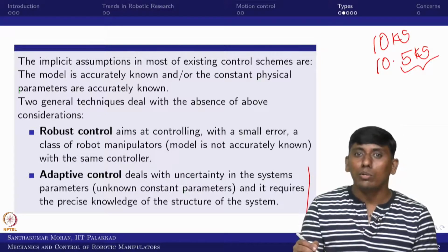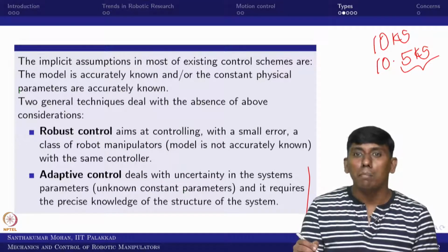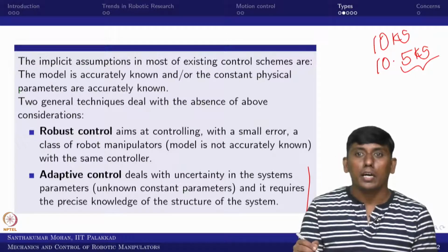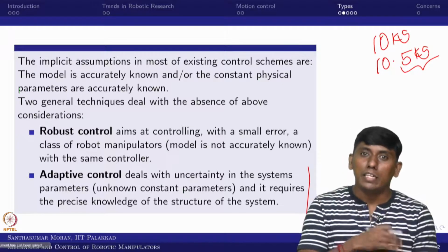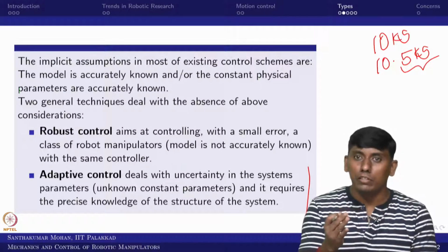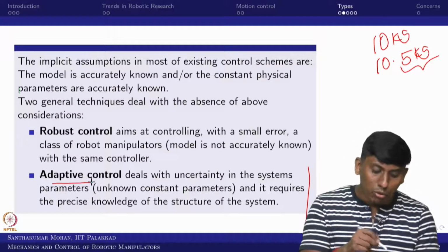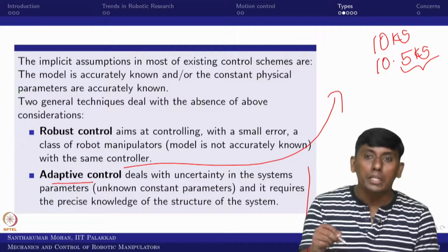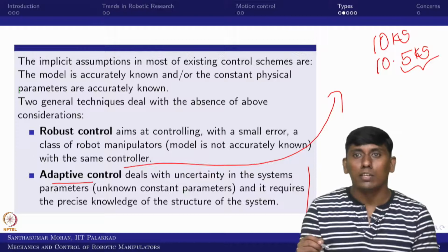The adaptive control is more beneficial. However, the adaptive law may end up with the system being unstable, because adaptive control mostly depends on the previous state. If the previous state and the current state have a difference, and the disturbance is fast varying, then the adaptive control may end up with problems. Most adaptive control would be based on what we call the regressor matrix. We'll come back to what a regressor matrix is.